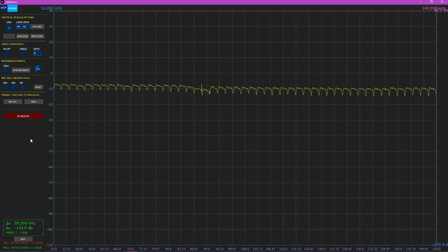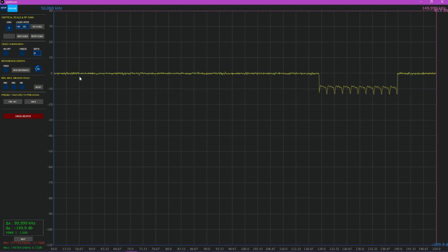Now you can see that once this is connected, the signal is slowly rising. As it does each pass, it is taking a relative measurement. Once each pass seems like it is moving relatively not at all, we can press the Set Relative button, and you'll see that it shifts everything to 0 dB to give us a nice average starting point of what our signal source should be.